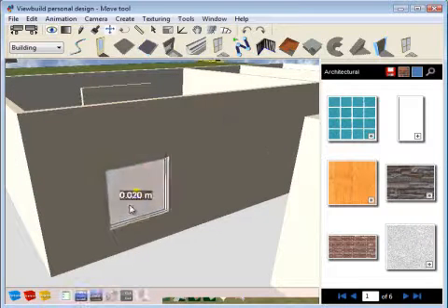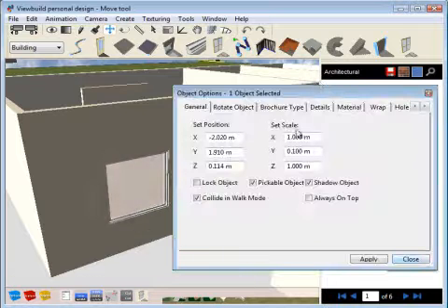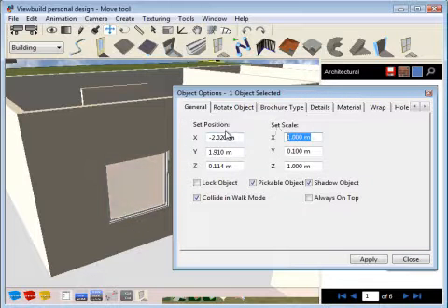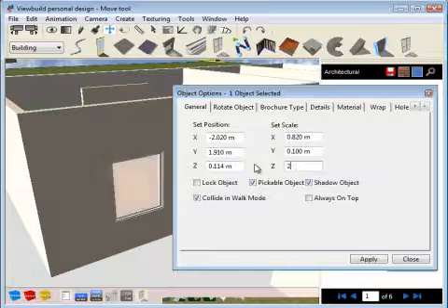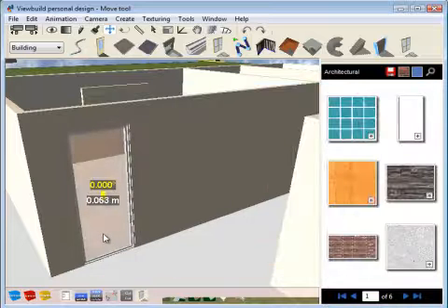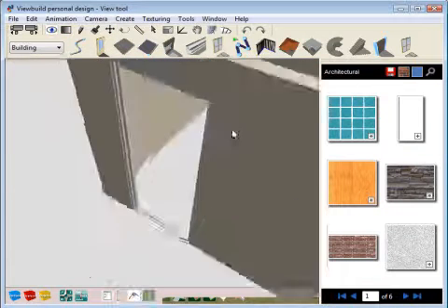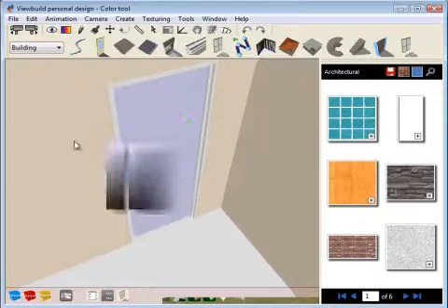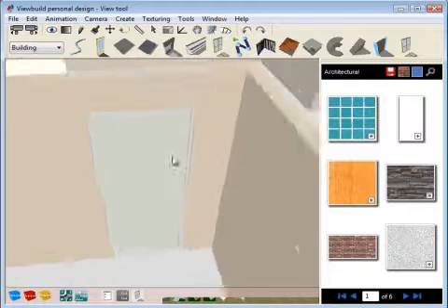But anyway, I tend to use the openings, and it's a powerful tool for simply typing in the desired width of a door, which is typically 0.82 wide by nearly 2.1 high, like so. And then we can either leave it open like that, or we can make it solid.